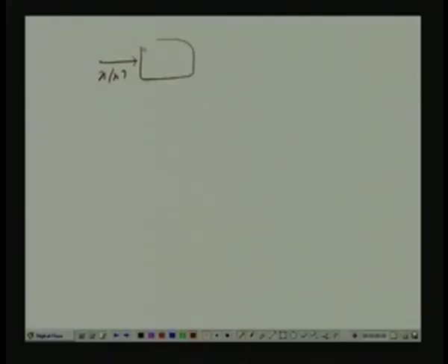What we have seen in the previous class in a nutshell was this. We are considering an optimal filtering problem like this. There was a random process Xn. It was passed through an FIR filter W0 dot dot dot WP. Instead of P, as I told you, I will change it to some other letter now, because I am using P as a vector for some other context. So, W0 to say WL, so L plus 1 coefficients. Output is Yn. There is a desired response Dn.